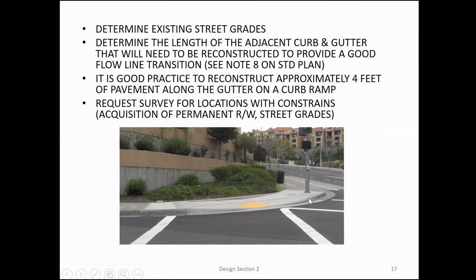Well, that's why you either reconstruct more, or like I was saying, adjust your edge of gutter here. If you're reconstructing the roadway, you lower the edge of gutter. I leave that up to you when you design, but you either reconstruct more. Jefferson is going through that right now. You either reconstruct more curb and gutter, but you've got to make sure the water flows. I don't think water is flowing here.